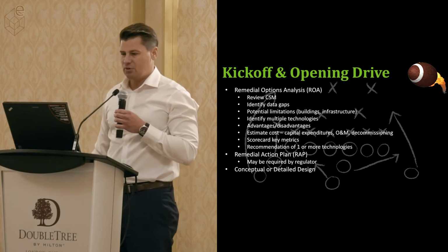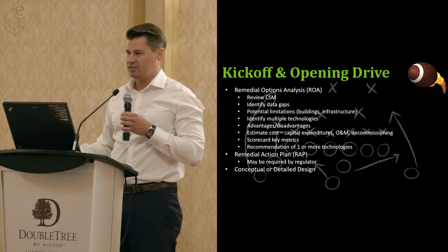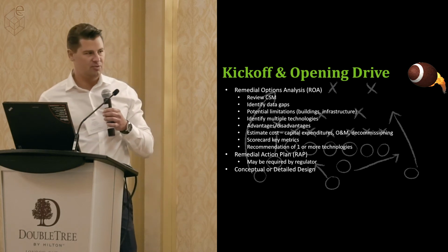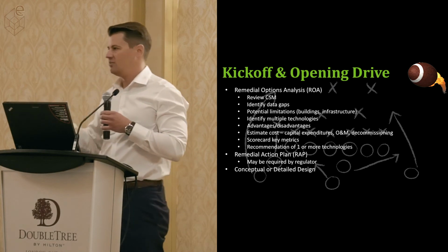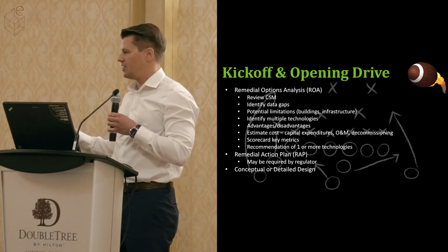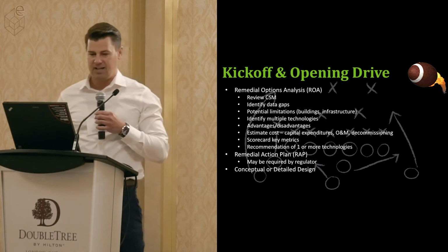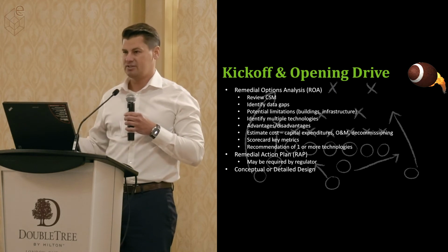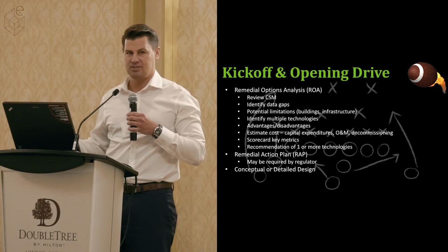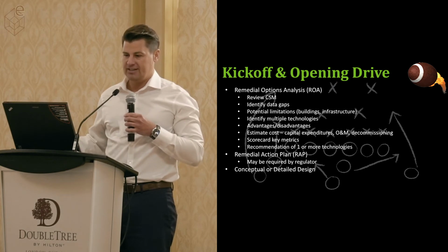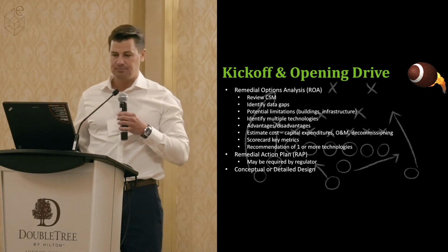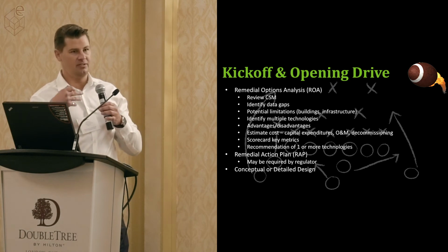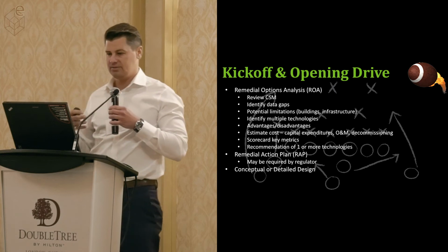So during the kickoff and opening drive, this is when we want to sit down and typically do a remedial options analysis. So we'll review the conceptual site model, which is all the phase 1, phase 2 environmental site assessment information. It was one of those boxes that Sean had in his presentation. So we want to really understand the conditions, the extent of the impacts, the characteristics of the hydrocarbons, look at any data gaps we might need to fill along the way, identify any potential limitations that might affect the technologies that we think have value here.